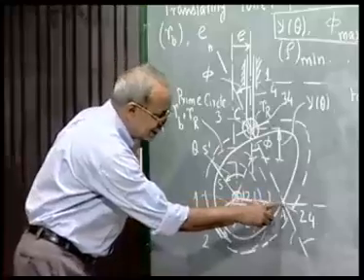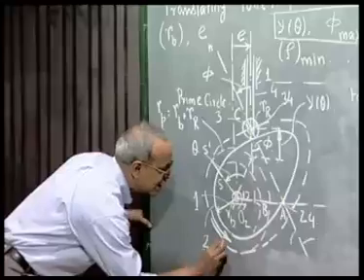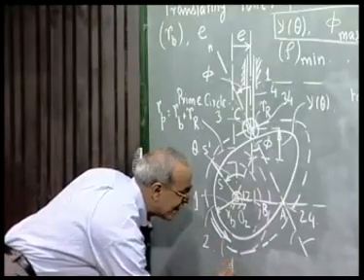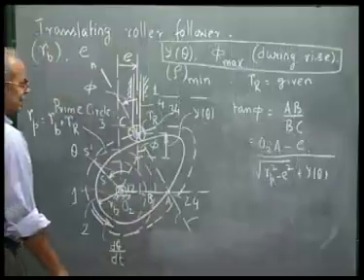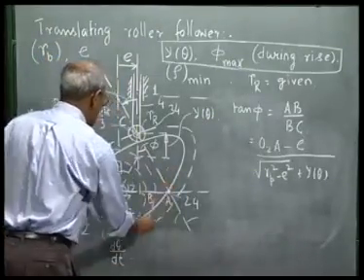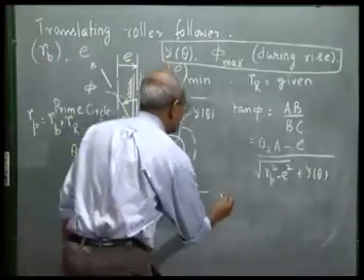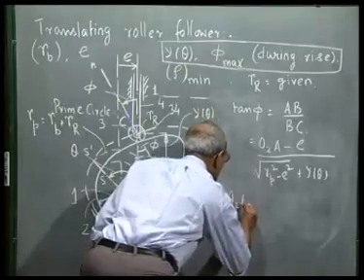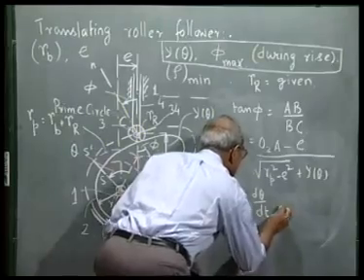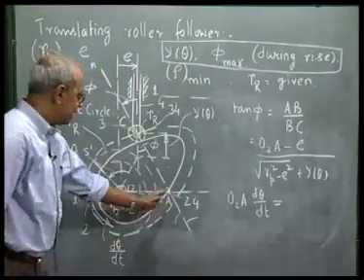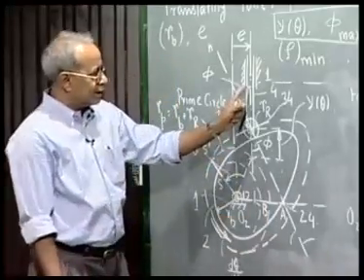So if I consider this to be a point on body 2, that is the cam which is rotating with constant omega, say constant omega d theta dt, then the velocity of this point is upward and the magnitude is O2A into d theta dt. So I can write O2A into d theta dt, that is the velocity of this point 2, 4 in the vertically upward direction.